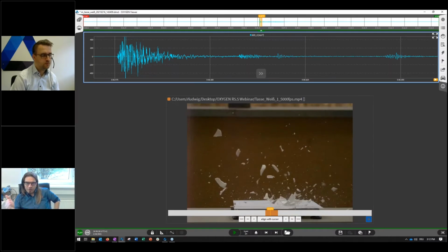So you can now transfer approximately double the amount of data than before. This was made possible by using a so-called Bayer format as the standard format for transferring the data from the camera into the software. Next, for rendering the video in the software, the H.264 encoder is now used by default. The big advantage is that this encoder is rendered on a separate chip, which is available on the CPU of the system.